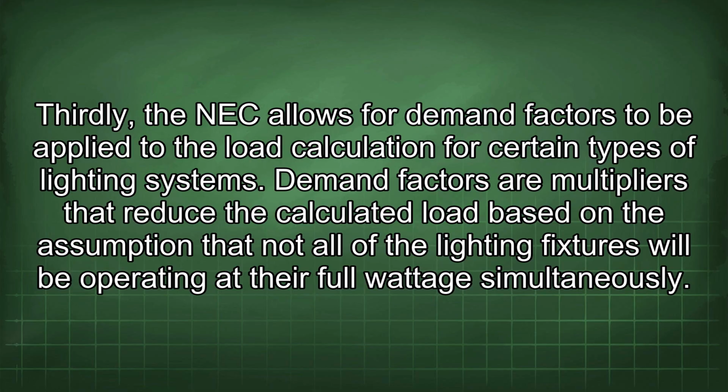Thirdly, the NEC allows for demand factors to be applied to the load calculation for certain types of lighting systems. Demand factors are multipliers that reduce the calculated load based on the assumption that not all of the lighting fixtures will be operating at their full wattage simultaneously.